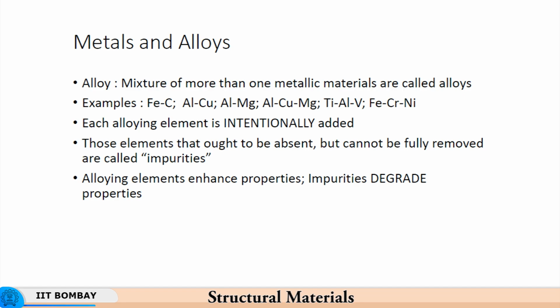We know stainless steels have iron, chromium, nickel. So now only iron can get corroded, only iron can get oxidized. You find oxide scales forming on iron articles. The durability is very low, degradation is faster. But when chromium and nickel are added, you get what is called 18-8 stainless steel, which we use for utensils at home. And these utensils last for years together without any degradation, something that wouldn't have been possible if only iron were to be used.